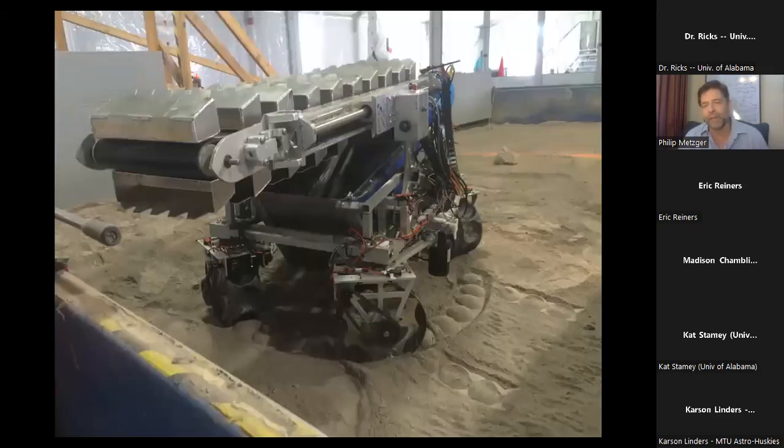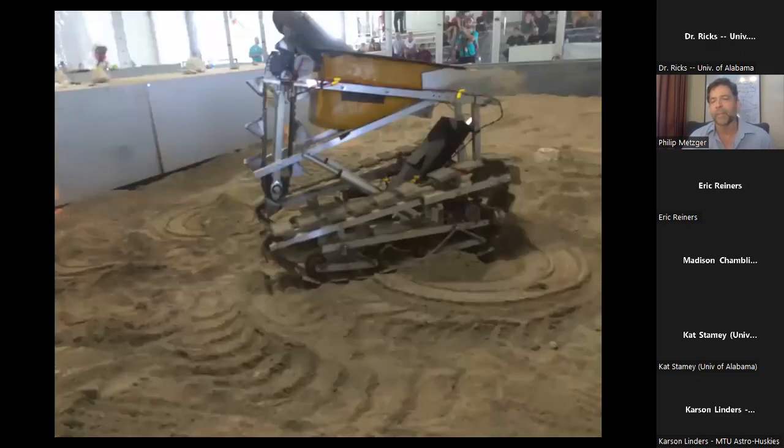Okay, different steering methods. Steering is important, it turns out. This is an example that roboticists call independent explicit steering, because each wheel can be turned independently and the vehicle has a lot more degrees of freedom in its ability to move around. This is tank steering, and you see I mentioned when you're steering with a track vehicle, you scrape dirt in the side, you can see the pile of dirt that's building up right there. And that dirt, as you're turning, is getting pushed into the tracks. So that's one of the challenges of track systems.